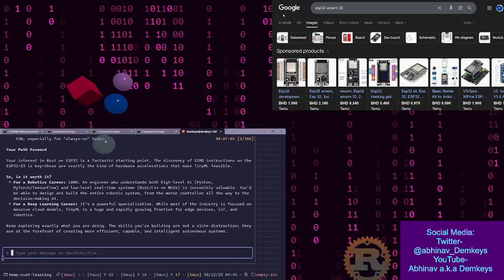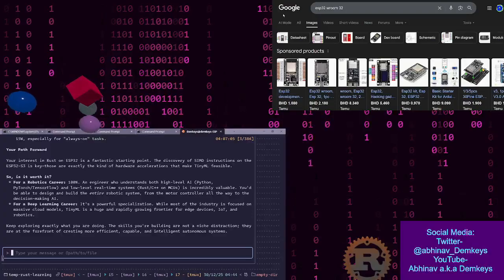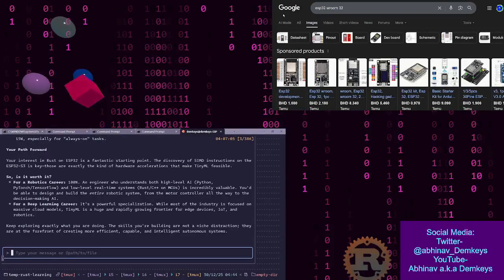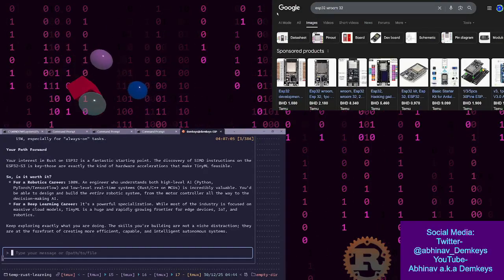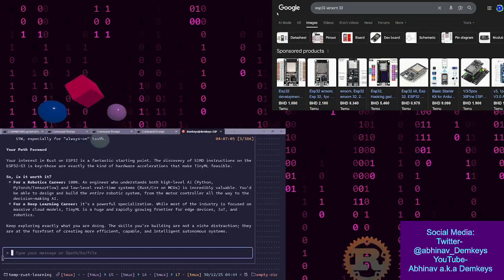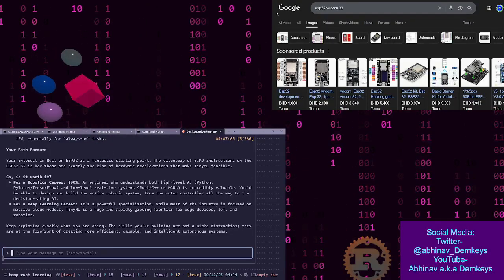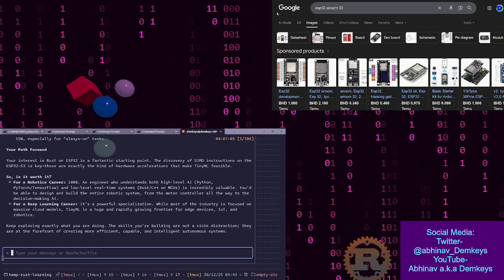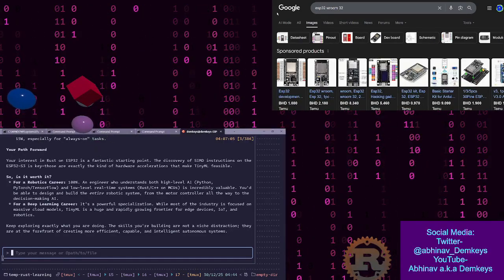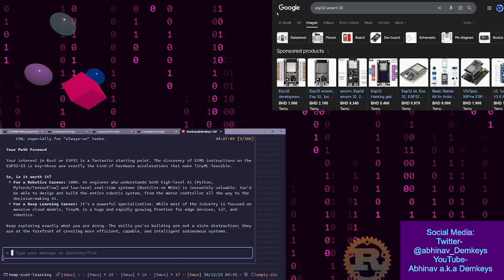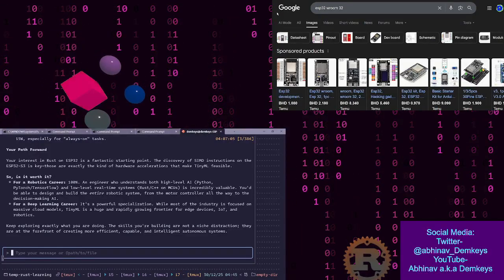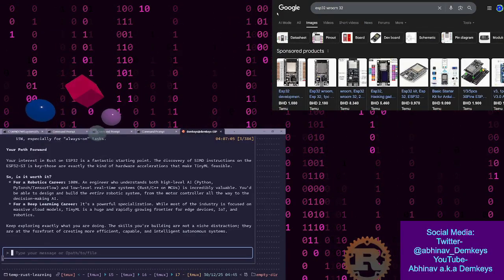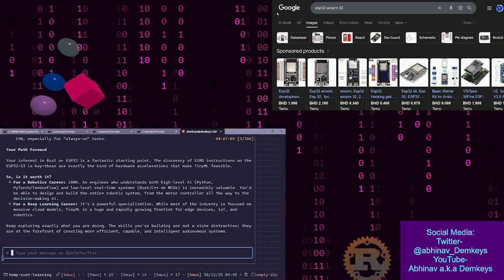Okay. Why does it get hot? The ESP32 usually runs cool, but two things make it heat up faster. One is Wi-Fi/Bluetooth. The radio power amplifier generates significant heat, and another thing is fast clock speeds, running at 240 megahertz. Oh yeah, you can actually set the speed for the processor. I forgot about that.